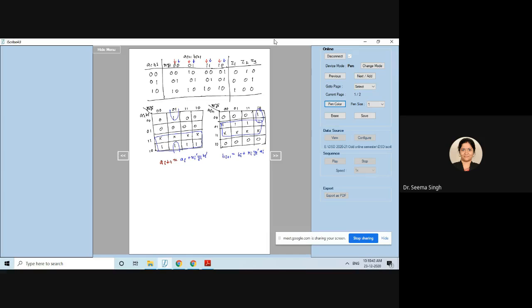Now I am writing the K-map and getting the equation, that is fine, but you can understand this equation otherwise also. What you can see here is Ai+1 will be equal to Ai. This is the case when the MSB only says that one specific input is high. So if this is 1, your Xi and Yi will not be dependent upon.